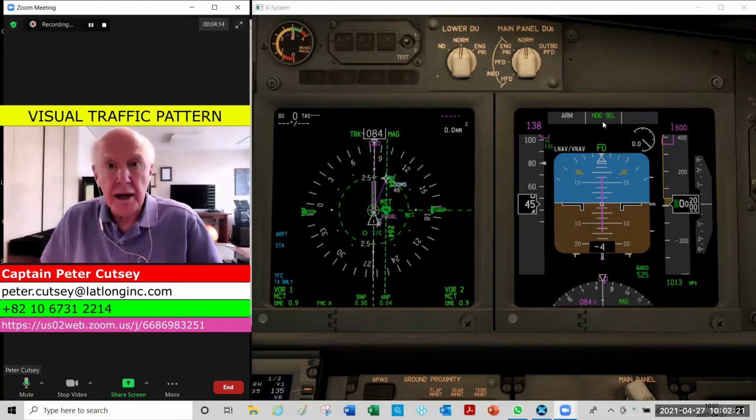In the airplane, when you're flying it, you'll be flying without auto throttles once takeoff thrust is set, and without command bars. Today you'll see them in view because I'm by myself on the flight deck. The whole idea of this exercise is to get to know the pitch and thrust references on the 737 in a flap configuration.